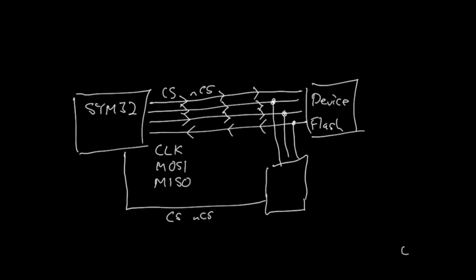So it does use more pins than, say, if we were using the I2C bus, but because we're not doing the additional things like sending the address and all of that sort of stuff and having the acknowledgements happen over those signal lines, in some ways we can actually get slightly better performance over SPI than we can with I2C.